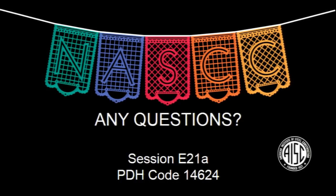Oh, that's a great question. Yeah, load height effects. There's been some research done by Todd Helwig and others that has shown a very simple way is just to use a modifier of 1.4. And the SSRC guide goes through that procedure in detail. It's just a matter of whether that 1.4 is dividing C sub B or multiplying C sub B, right? That's where you're talking about whether it's helping or hurting, because the cross sections want to twist, right? So yeah, I would really recommend that you look in Chapter 5 of the SSRC guide, and it'll explain to you how to account for load height effects.